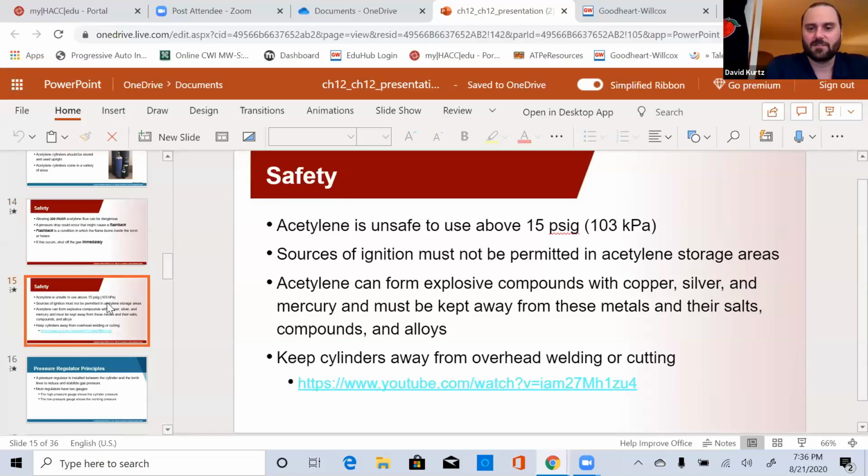Acetylene is unsafe to be used above 15 psi. Again, we're going to hear that. This is, what, the second or third time already in this video. You're going to see it, hear it all the time throughout the book. Chapters 13, 14, and 15 are all dedicated to oxyfuel welding or cutting. So 15 psi, they stress, stress, stress. And like I said, we shouldn't be anywhere near that, so we shouldn't have to worry about it.